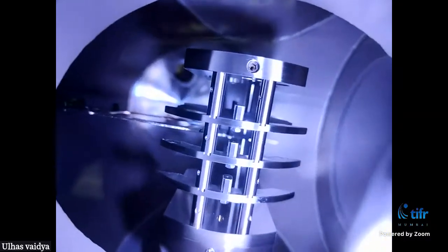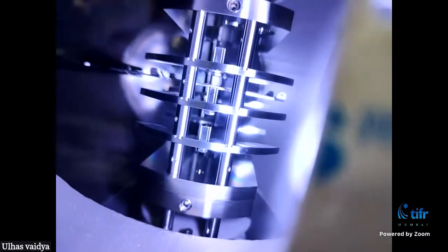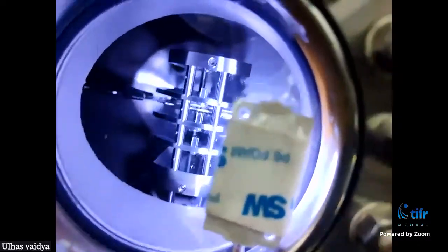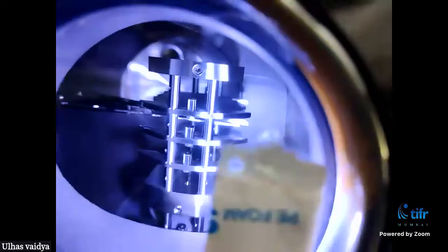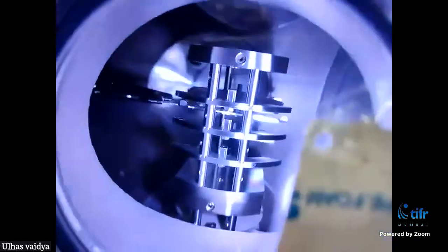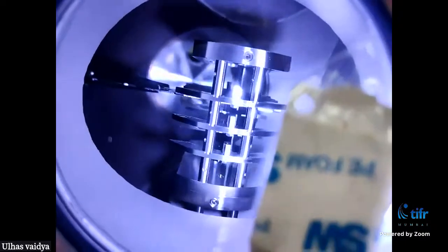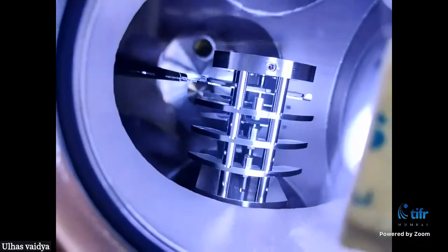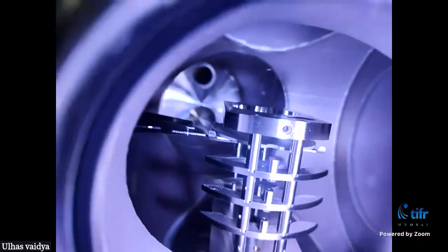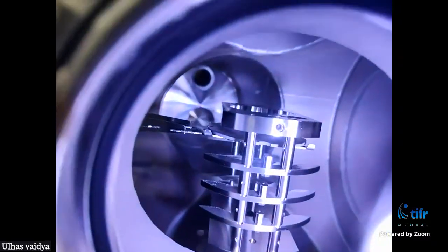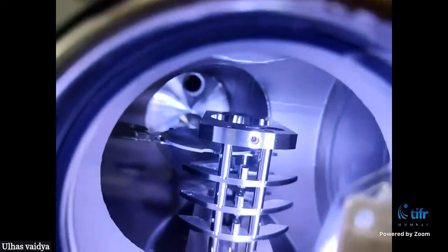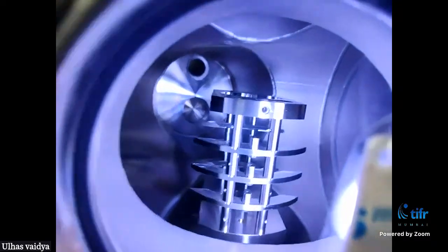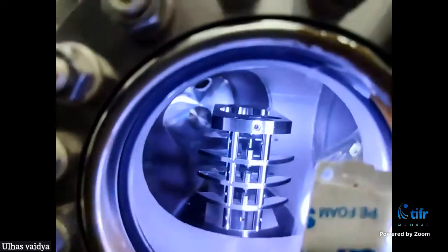It is very important, because if the arm bends, we have to open this chamber again and get the vacuum again, which takes 2 minutes. Any small mistake takes a long time to correct. And now you can see I have transferred the thing from the vertical arm to the horizontal arm. Now we will take it out again, slowly. Then the vertical arm will go down, so that if we come again in this direction, it doesn't collide.